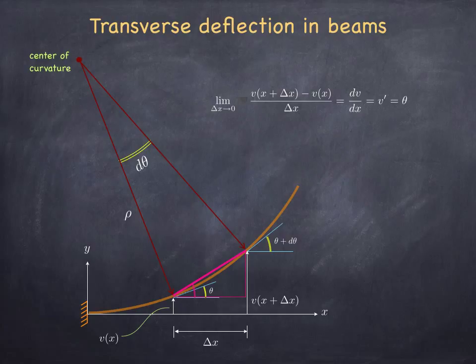It's rather an increment of it, and you can see this from simple geometry: if the angle that the neutral plane's tangent makes with the horizontal direction is theta on the left end of the segment, then if you sweep a d theta segment at the center of curvature, the same angle will have been incremented by an identical increment d theta. Hence, it's appropriate to use the same name for those two angles.